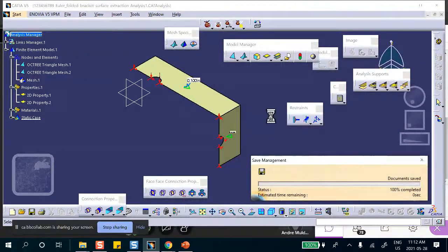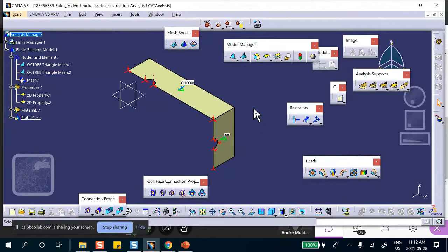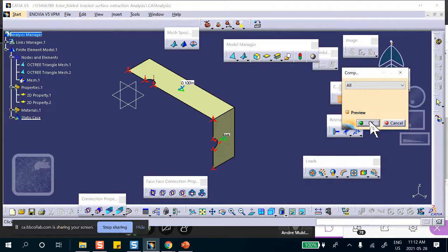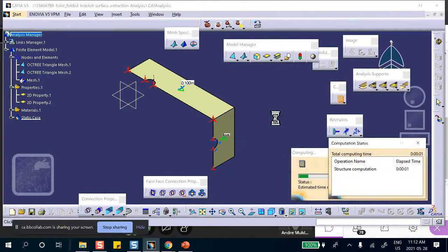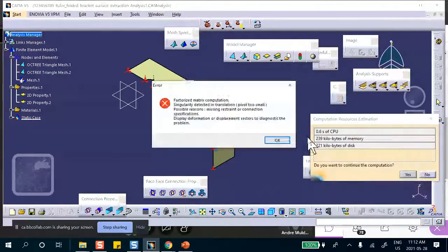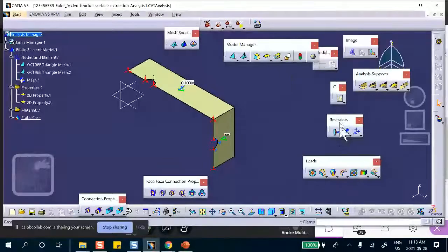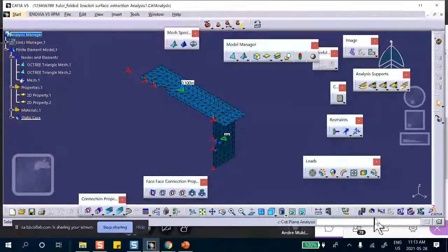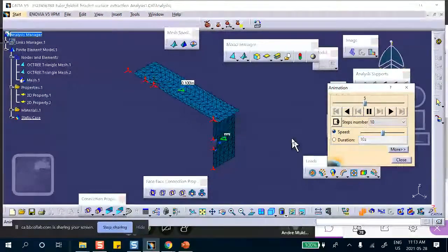Okay, good. Now, let's run it and see how it bombs out, and we can see that that seam is going to cause a problem. There. Okay, let's animate it. Maybe it'll tell us something right there. And you can see that these nodes were not talking to each other. They don't know that they're attached to the same thing. They don't know that they have to move along that line. So this top is basically moving as a rigid body.